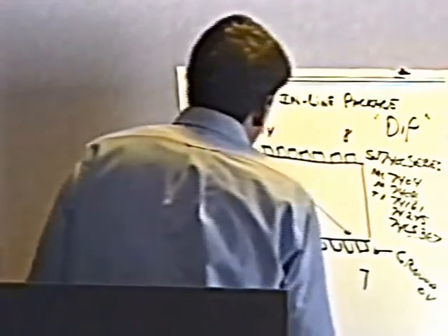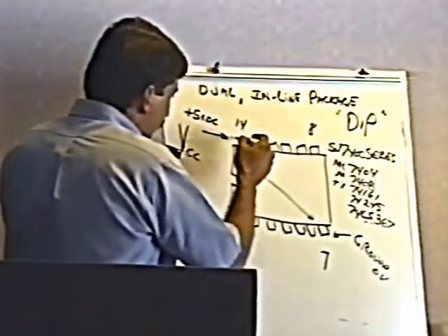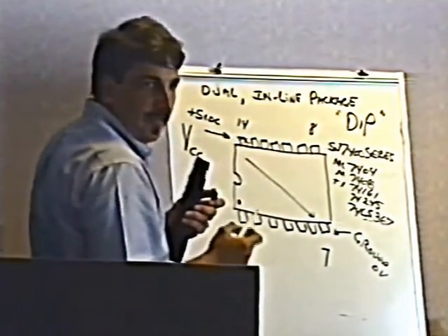See how I'm pressing on this? I'm not even looking at it now, and I'm holding it on there. I could never do that if I tried to put it just right on top of the pin. I'd have to be very careful to not short the two together and slip. So by putting it in the corner like that, you can jam it up in the corner and it won't slip off. So make sure you do that because the power is turned on. If you try to put the meter probe right on the top of the pin, you'll slip and short the two together.